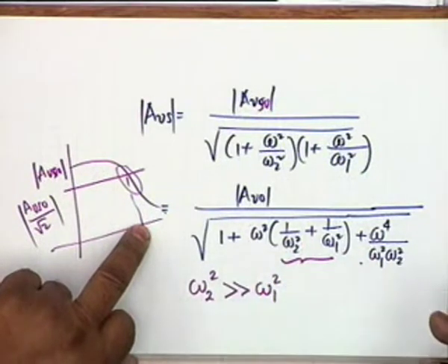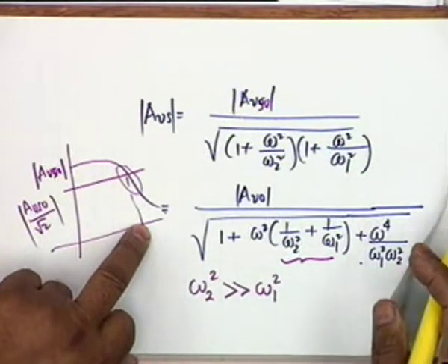Therefore in this particular case, as in other cases to come, as long as omega 1 squared is much less than omega 2 squared, as long as it is 1 decade below, meaning a ratio of 10, we are perfectly in business, which means that omega 1 and omega 2 need to differ only by a factor of 3.2, the square of which is approximately 10.